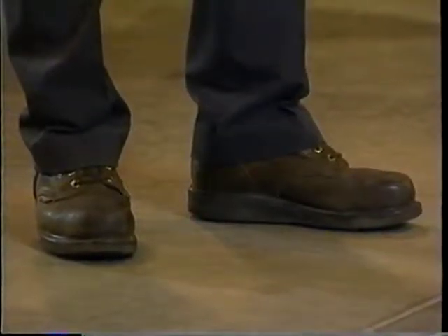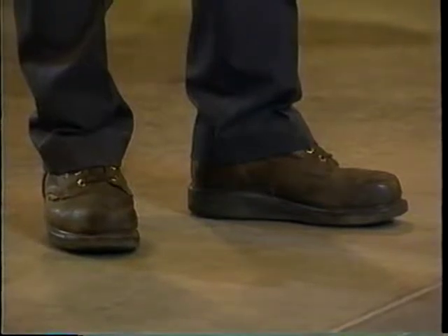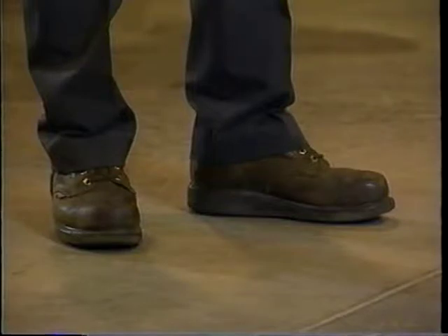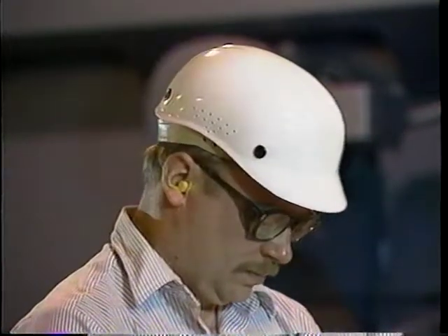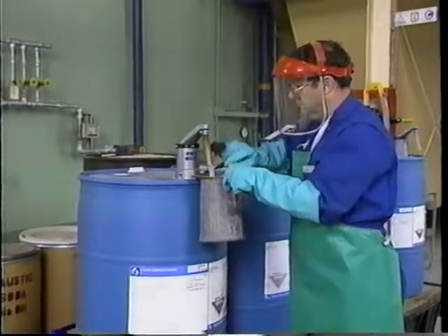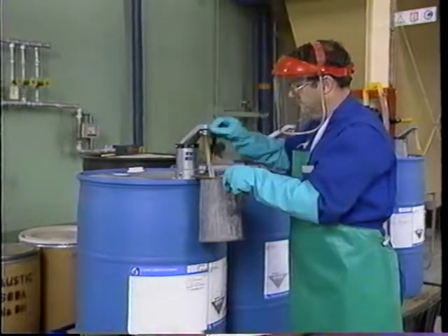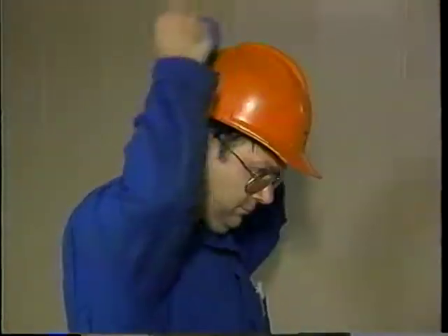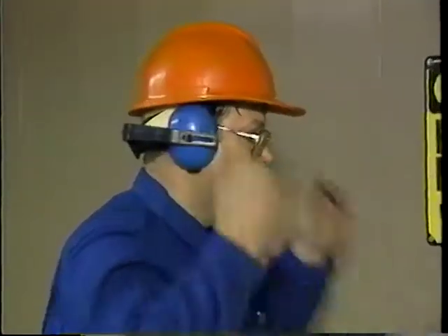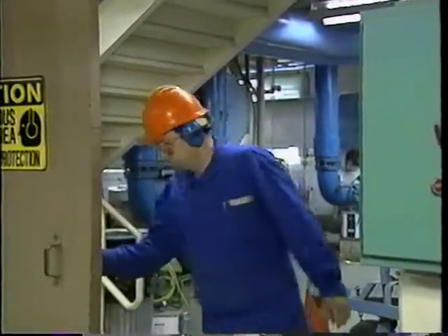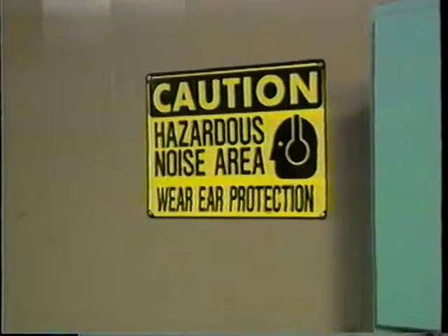Safety shoes with durable, oil-resistant soles are recommended. Steel toe shoes provide protection from falling objects. A safety helmet should be worn in areas where overhead danger is possible. Proper eye protection should be worn when working with feedwater chemicals, inspecting the fire in the furnace, or other potentially hazardous activities. Ear protection may be required to prevent injury from noise. Plant procedures will dictate specific boiler operator protective clothing and accessories.